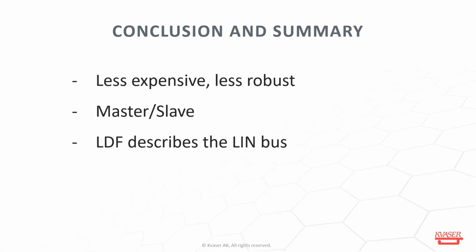LIN works on the master-slave principle. One master controlling multiple slaves. One master setting the tone for multiple nodes. The LDF describes the LIN bus. That is the configuration file that you need for your LIN system.